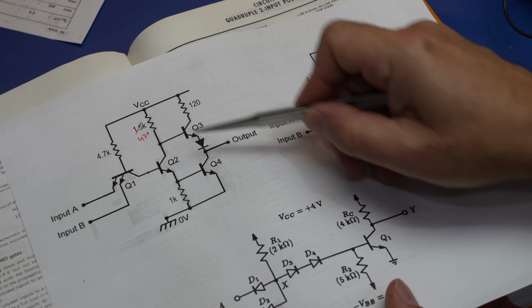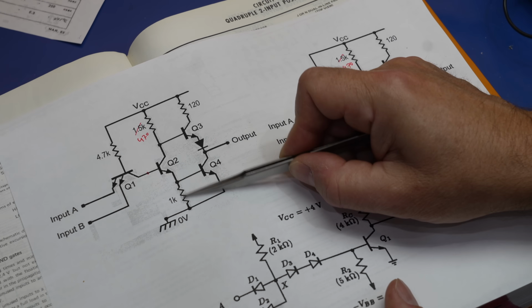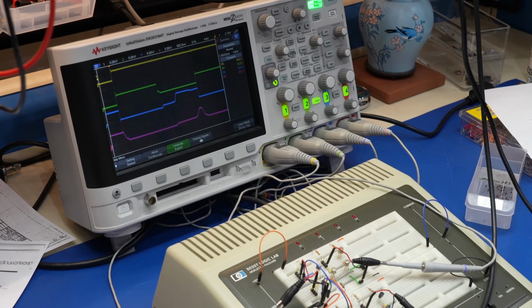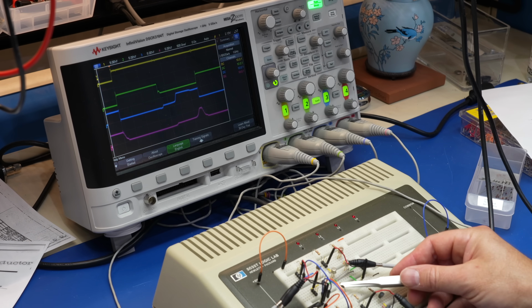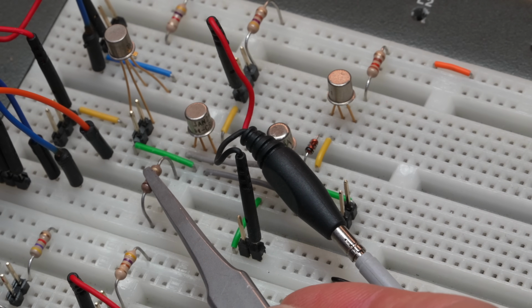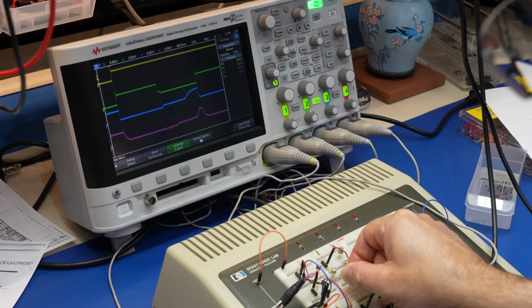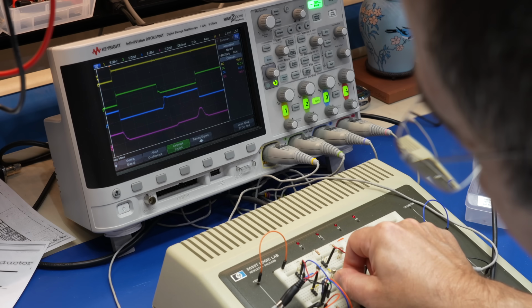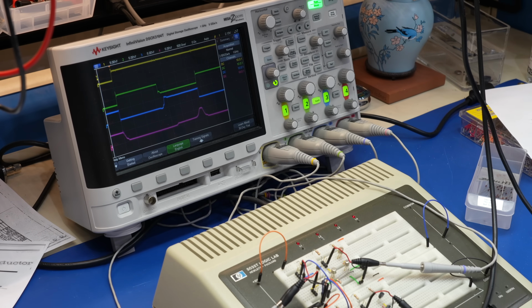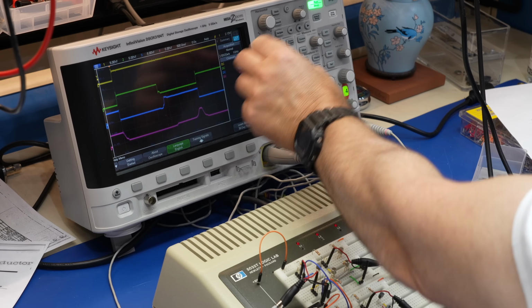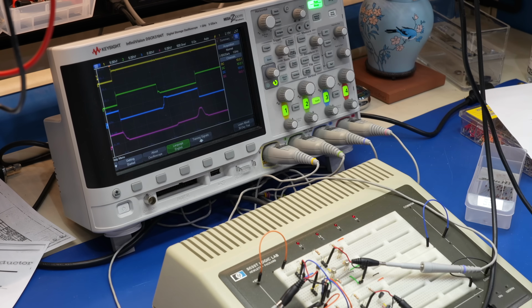So what I'm going to do, since I have a fairly low resistance here, I can lower this a lot, and this should enable Q4 to get out of saturation way faster. So let's help that poor transistor to get out of saturation and replace that 1K resistor with something way lower. I'm going to try 120. And since I have a transistor of Q2 driving it, I can go fairly low here. It's going to be able to pull it up when it needs to. And yeah, you see it's already much better. I think I could go even a little faster, a little more than that.